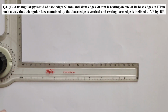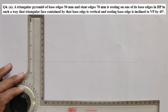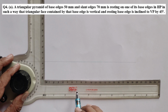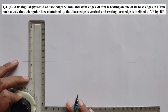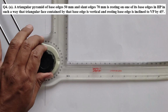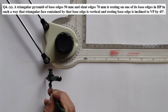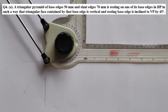As the question is given resting on HP, the true shape of the base is visible from the top view, so you'll draw the top view first. Taking a vertical projector here, the distance is not given, so let's take 30 mm. Then you have to take the base edge of 50 mm sides here. Take the distance 50 mm in your compass from here, then draw the arcs, completing the base.